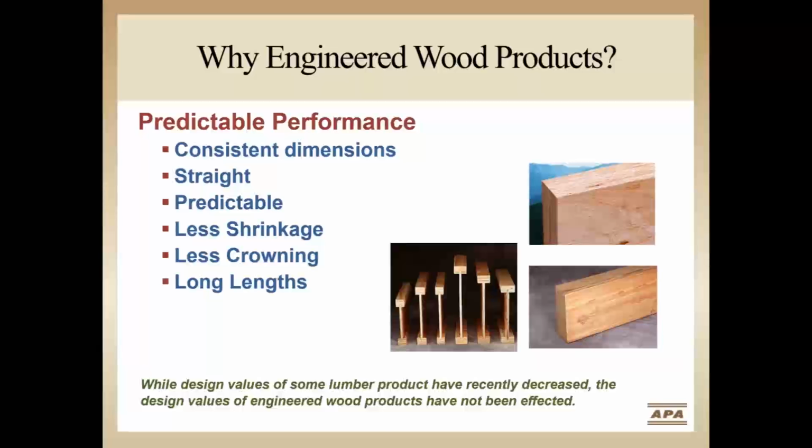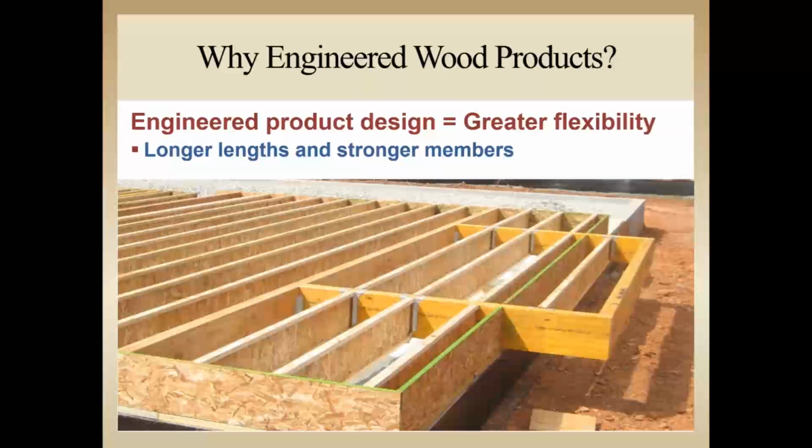Another key reason for their popularity is the longer lengths that are available, resulting in fewer pieces to purchase and increased design flexibility. Using fewer pieces increases profitability since less framing is needed and time is saved during cutting and fitting. Longer spans provide the designer with more options for use of the interior space by increasing spaces between supporting walls and beams, resulting in more saleable floor plans. Stronger members can also mean fewer pieces because floor joist spacing can often be increased.